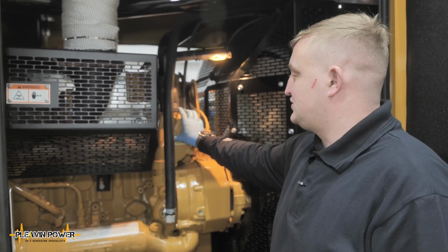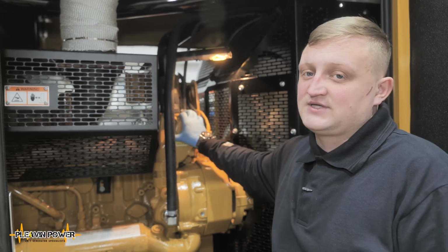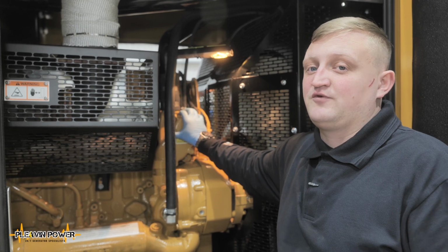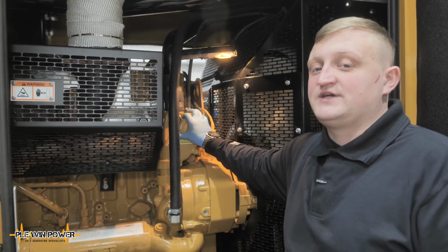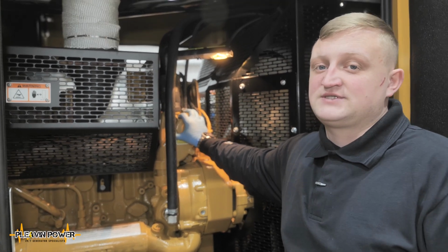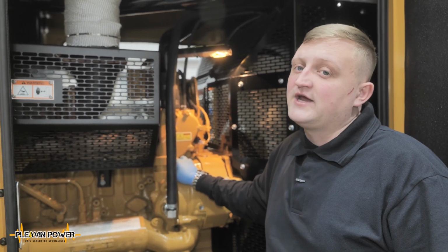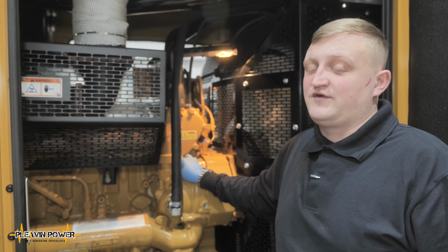The thermostats need to be changed along with the gaskets that surround the thermostat housing itself to ensure your engine can remain reliable and operate at its optimal performance levels, and that you don't run the risk of having a situation whereby the thermostats end up being stuck open or stuck closed, causing the engine to fail from either overheating or overcooling, which would leave the engine unavailable for operation.